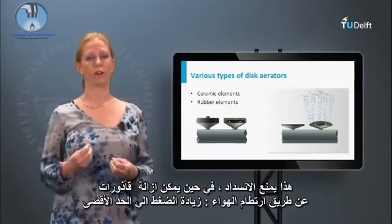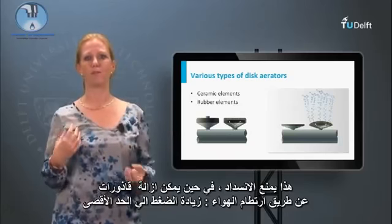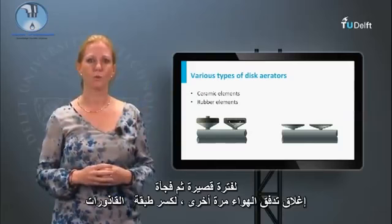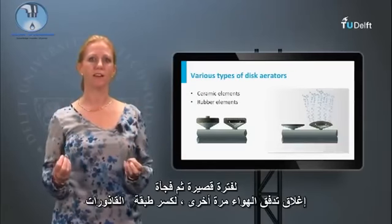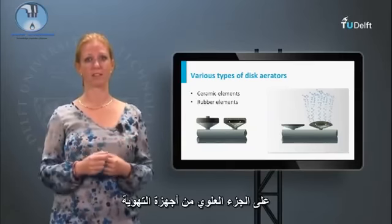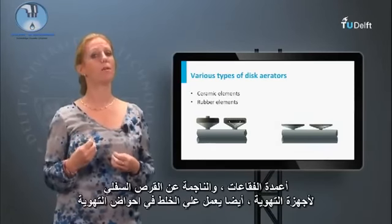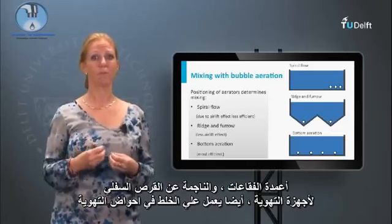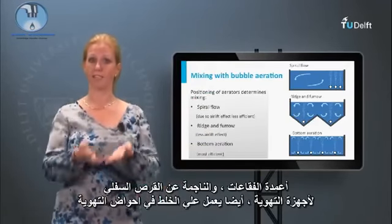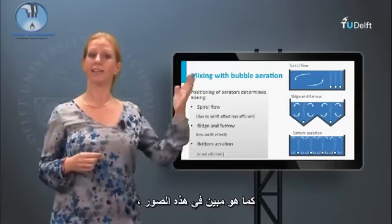This prevents clogging, while fouling can be removed by air bumping. Increase to a maximum pressure for a short while and then suddenly close the airflow again to break the fouling layer on top of the aerators. Bubble columns caused by the bottom disc aerators also introduce mixing in the aeration tanks, as shown in these pictures.